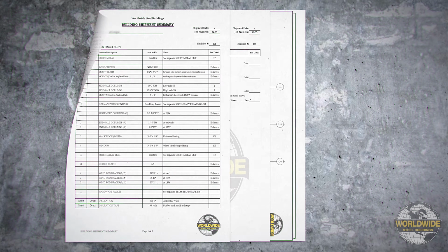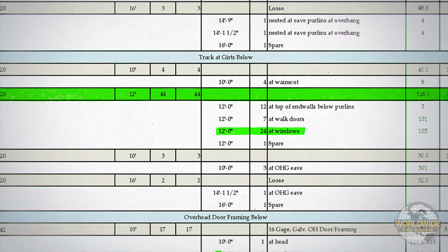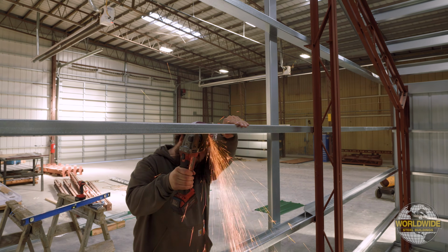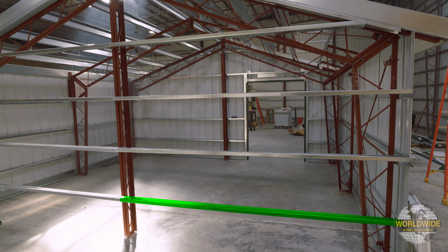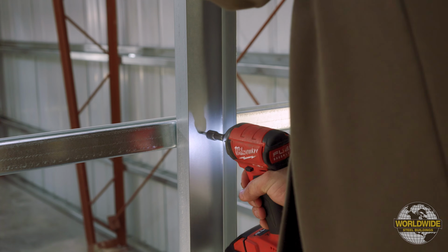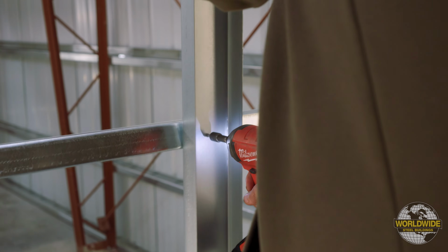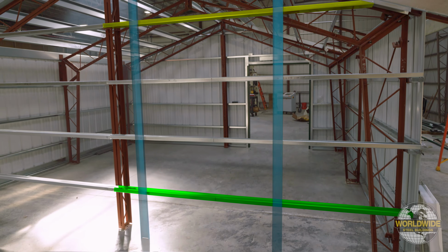Galvanized track has been supplied for the window framed openings and can be located on your shipment list as shown here. If you will need to cut a girt for jamb installation, identify the lower girt for jamb attachment as well as the upper girt for jamb attachment. Temporarily install galvanized material to stabilize any girts that will be cut for your framed opening.